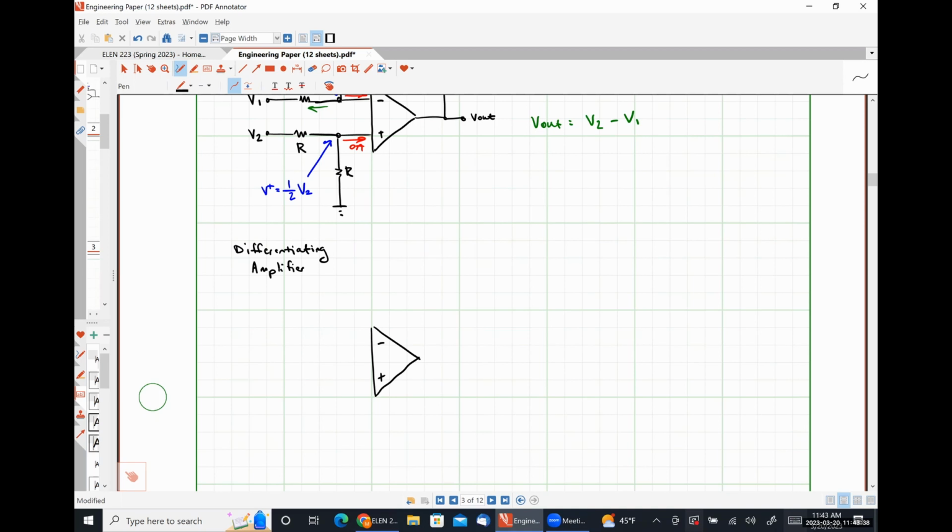I am going to derive things using capacitors. In practice, you will more likely use a capacitor to make an integrating amplifier or a differentiating amplifier than you will an inductor, because the tolerance on capacitors is better than the tolerance on inductors. So effectively, you're going to get closer to what you want using capacitors. But the theoretical relationships, it really does not matter. As a matter of fact, I make you derive one of them in one of your homeworks using inductors instead of capacitors.